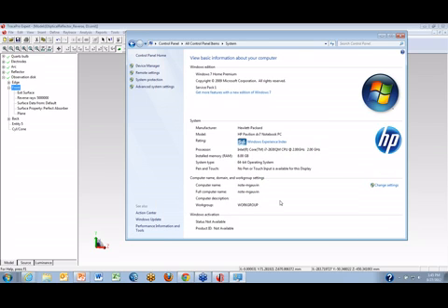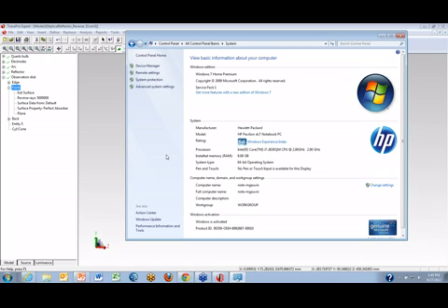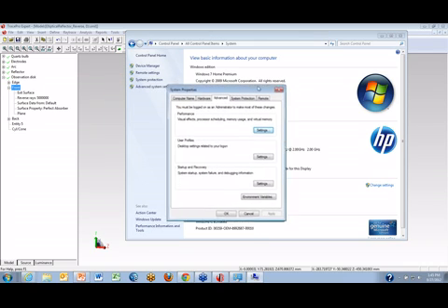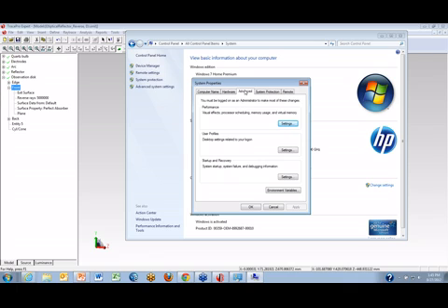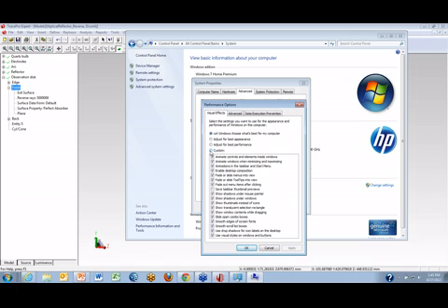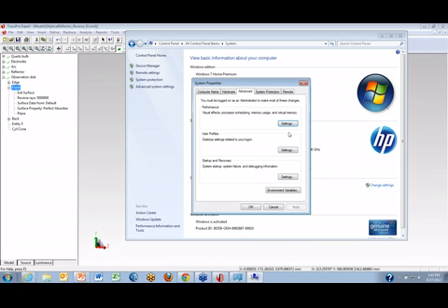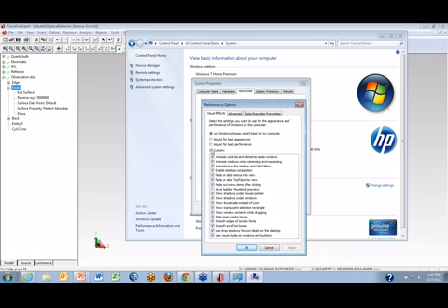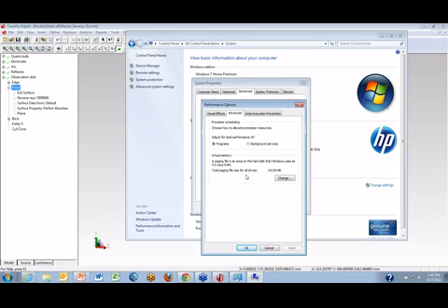Well, one other thing is that if you want to increase your virtual page size to have some of these big ray traces, go to your control panel, your system area, go to the advanced system settings that you see over here, go to your advanced tab, and you can change your performance calculations. In fact, if you go to the custom over here and you set that, you're going to see what your virtual memory is. And I've gone to the advanced tab here, and that's going to show you how big your total paging size is. If it's not big enough, you can increase it, and that'll allow you to do larger ray traces, just so everyone knows. That's pretty much all I have for everyone.